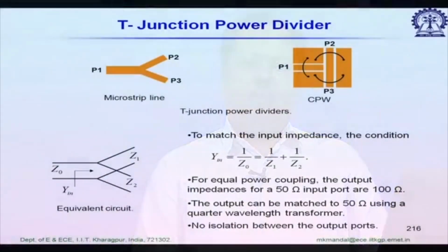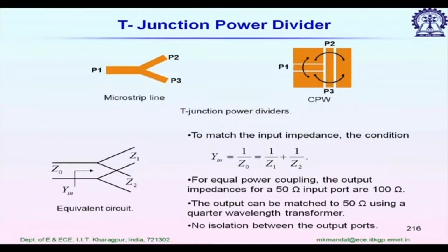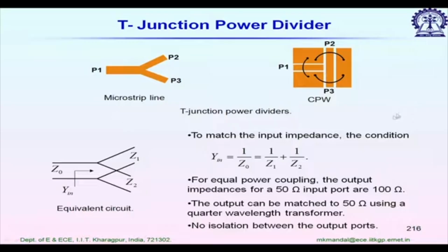Okay, so next topic is power dividers and couplers. Whatever we use at microwave frequencies, similar concepts we can extend to millimeter wave frequencies. The only thing is that we have to do frequency scaling of the components, and also we need to keep in mind the losses. So let's start with a simple T junction.